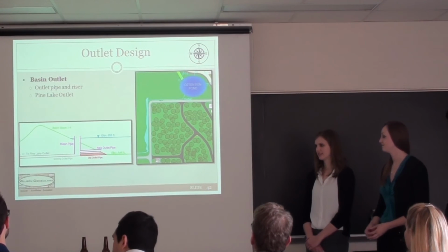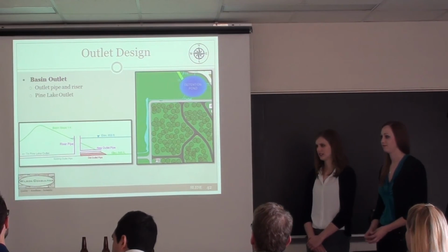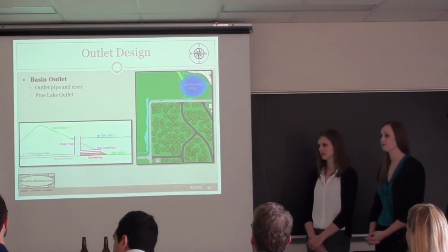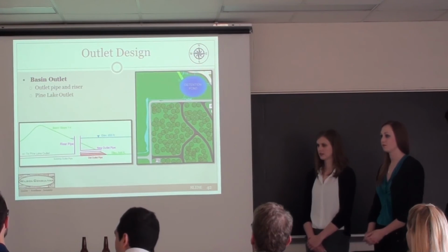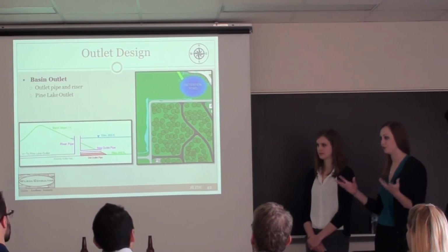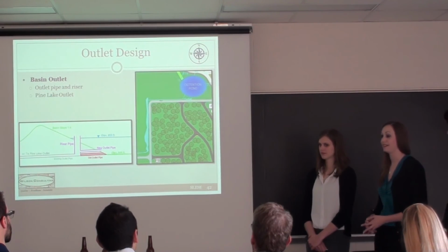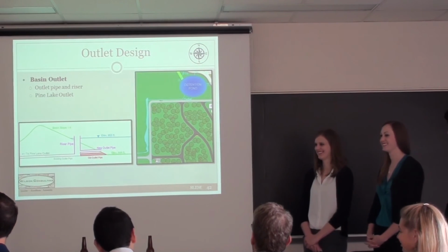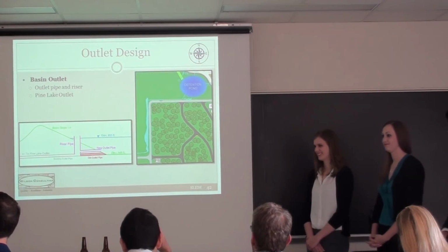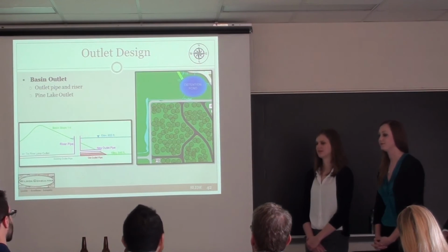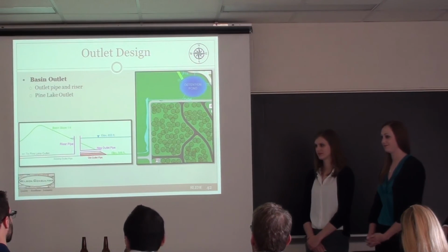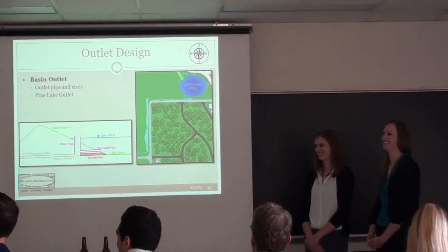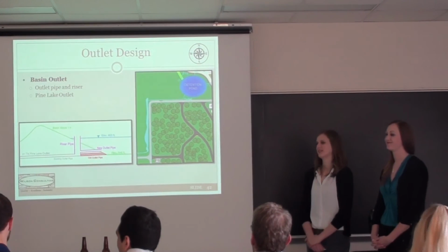You're going to have trouble with photosynthesis. 2 feet of water is not enough to stop growth on the bottom of the surface, so something's going to grow. Yes, we'll certainly be implementing a maintenance program for the basin. And you'll also have recurring problems with mosquitoes, except that you're going to deal with that with maintenance. Very good, very good. We thought of everything.